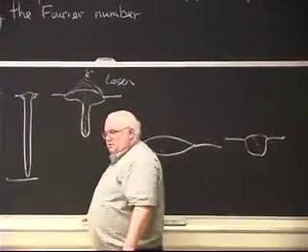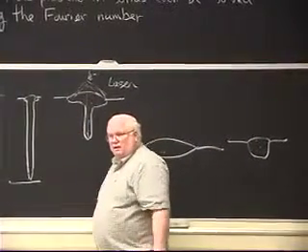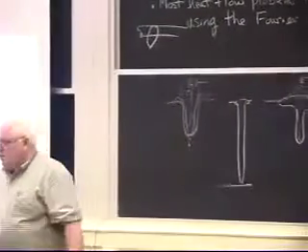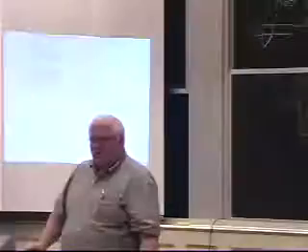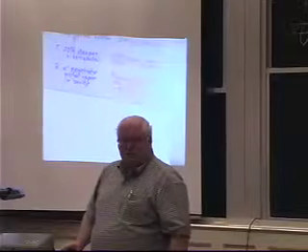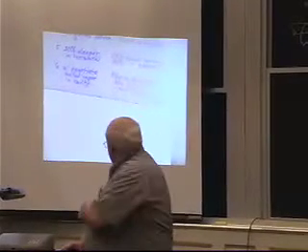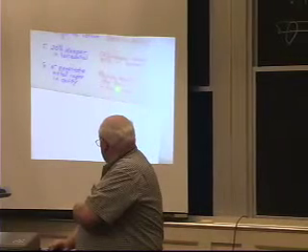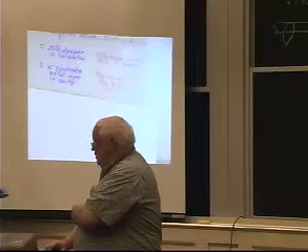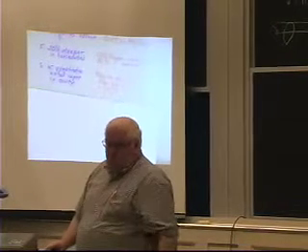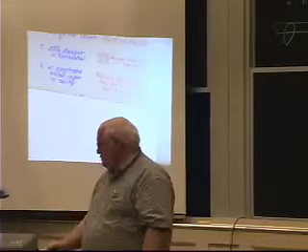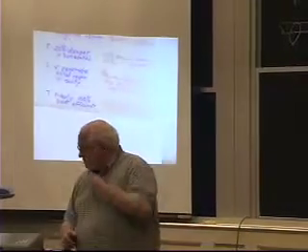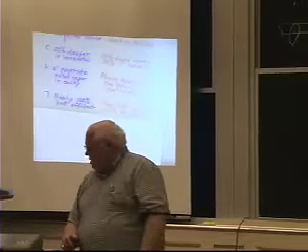This nail head is a result of a heat source that looks like a nail head. Okay, the molten region looks like a nail head, but the molten head is just mirroring the intensity of heat on the surface. Okay, and essentially those free electrons create a plasma above the surface that creates the nail head, which is not necessarily bad, but it has to be controlled. Okay, if you get the wrong shaped nail head, you can get some defects in there, solidification.